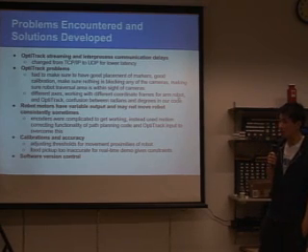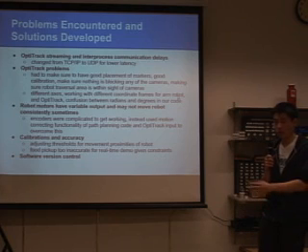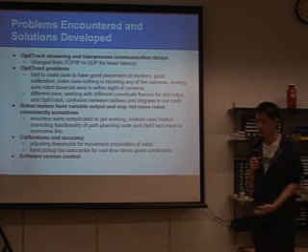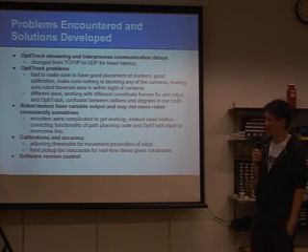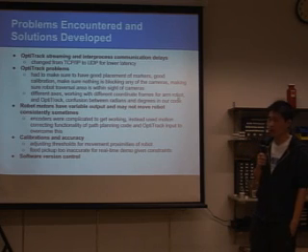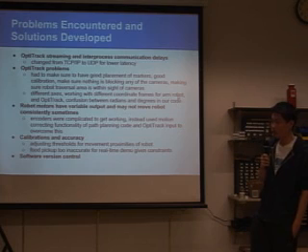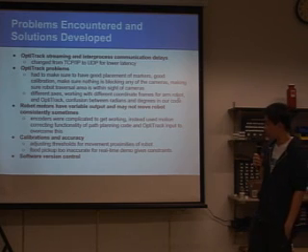So the problems we encountered when trying to implement all the details. First of all, the OptiTrack streaming was not very reliable. If, like Mark mentioned, someone walks while the OptiTrack is streaming data, then we'd probably lose the robot. Second, there was a pretty long latency when we were trying to implement the networking code with TCP protocol. So we changed it for UDP for lower latency.